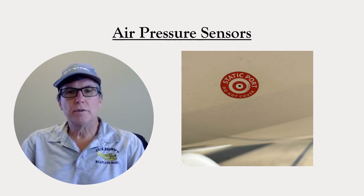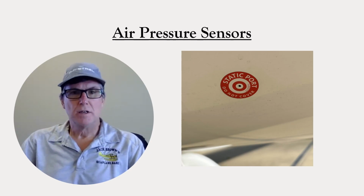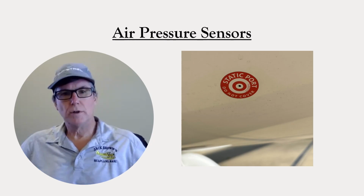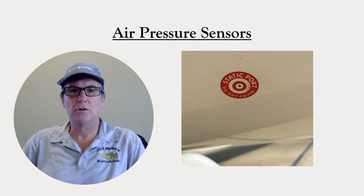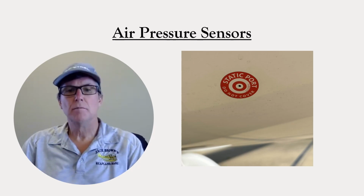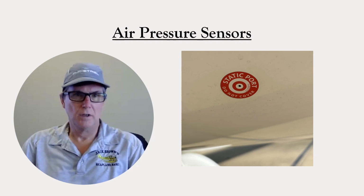The static port is a small hole, usually on the side of the aircraft. It's positioned to sense ambient pressure. That's the pressure that the air would have if it was not being influenced at all by the aircraft. Of course, it's impossible to not influence the air, but the designers will pick a location on the airplane that approximates that as well as possible.